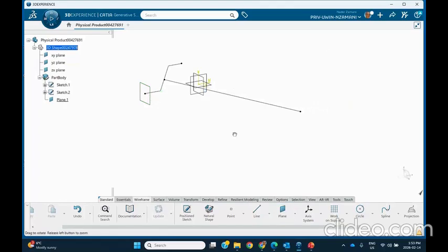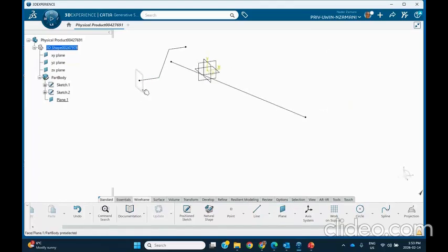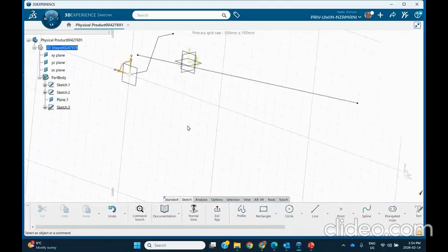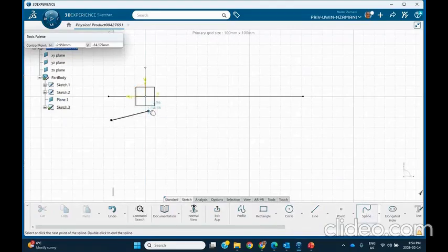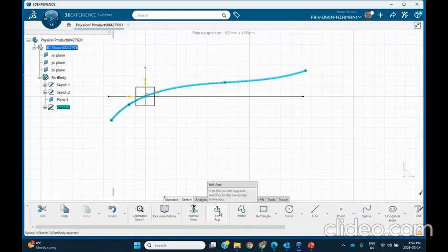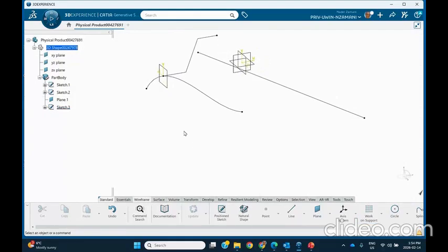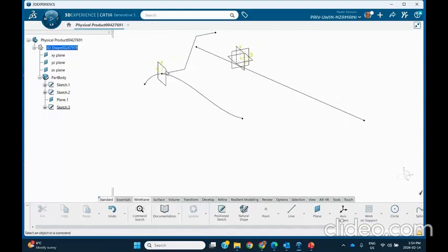All right. So what I did, on purpose, is draw a plane here, and I'm going to draw this second guide on this plane. So on that plane, I will sketch. Let me draw a spline, something like this. I'm going to make it go through that point later on, but that's not really the issue here. Okay, good. Exit. Notice that it just happens that this spline I drew in that vertical plane also goes through that. This guide does not touch the profile.